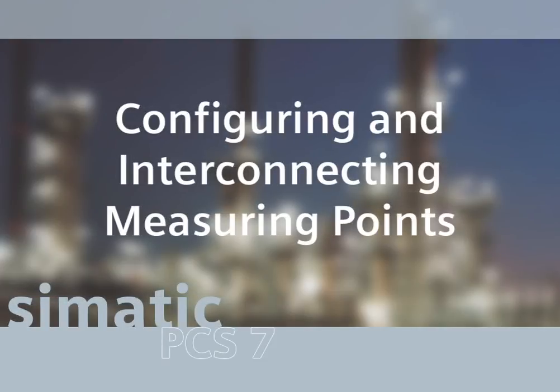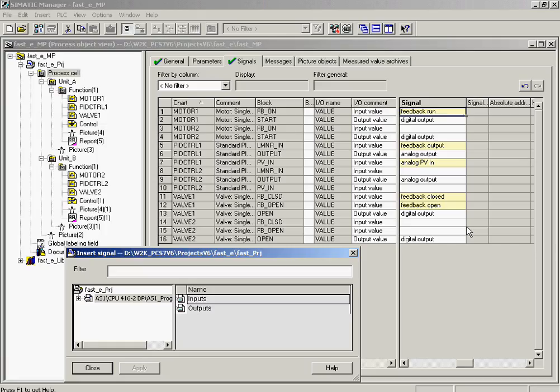In this sequence, we are going to show you how you can easily assign I/O signals to the individual charts and function blocks that are used in the application. We will use the symbolical names which have been defined previously and assign them to the corresponding measuring points. The signals are interfaced easily and conveniently in the process object view. In this view, it is possible to carry out all assignments globally, without having to open up each individual chart or function block one by one.